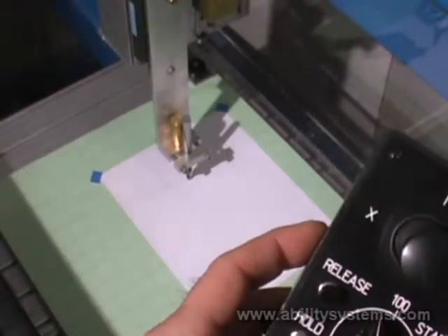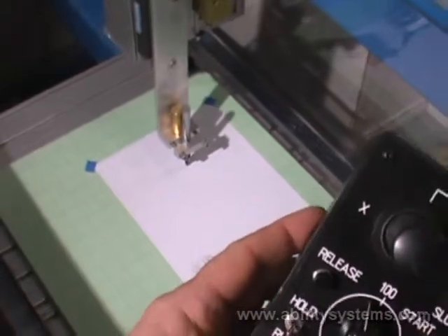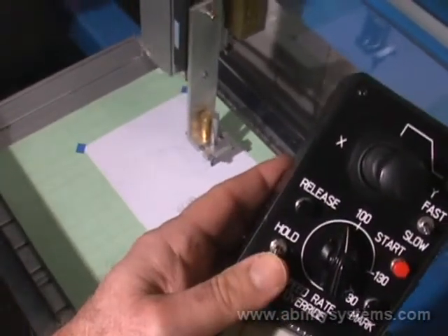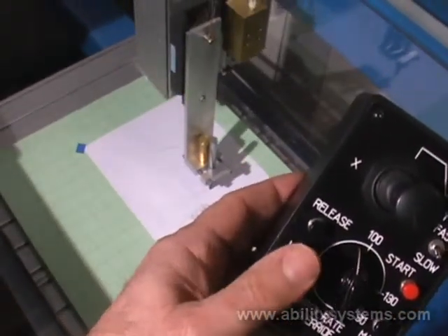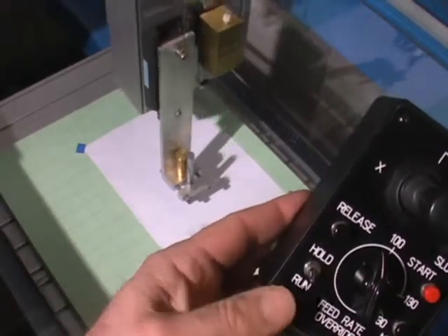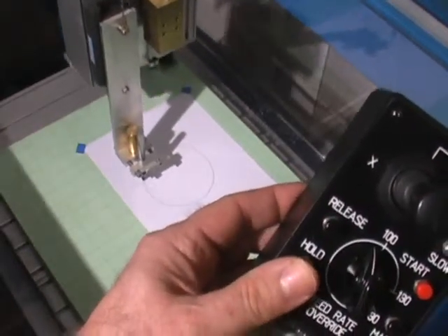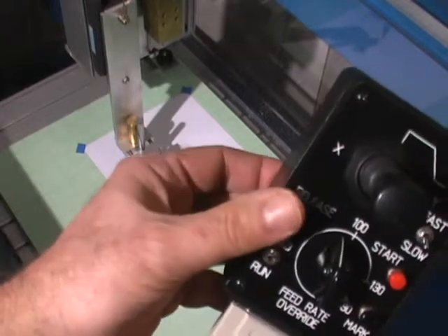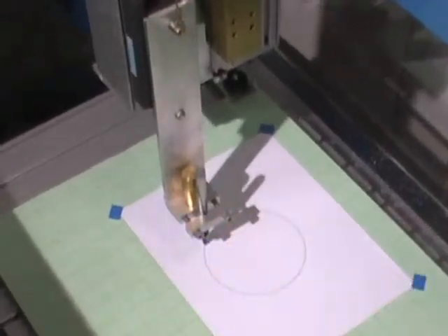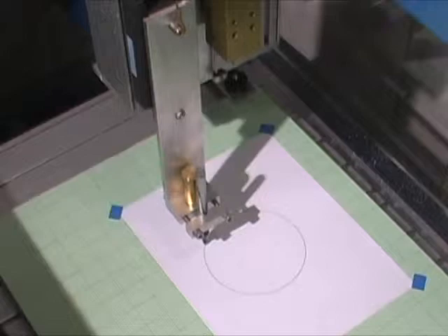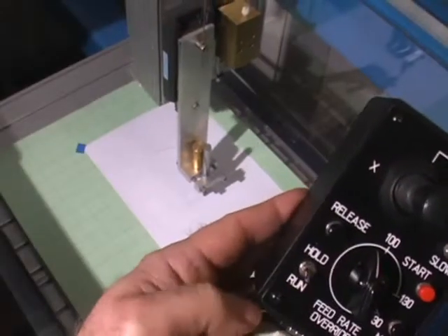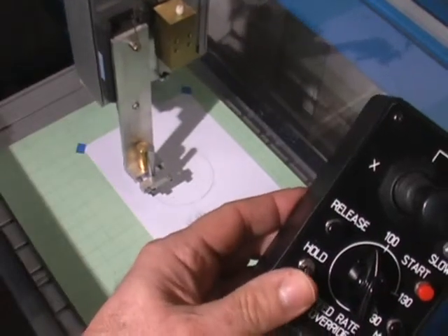Indexer LPT's feed-hold feature was designed to provide for controlled stopping whether or not accelerated motion is being employed. Activating the feed-hold switch will bring all motion to a decelerated and controlled stop. Position tracking is preserved. Deactivating the switch accelerates the motion into its resuming path.